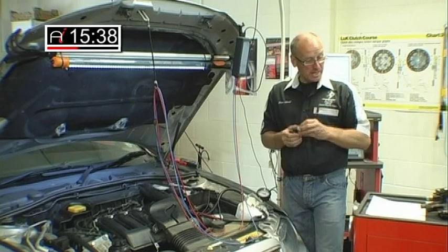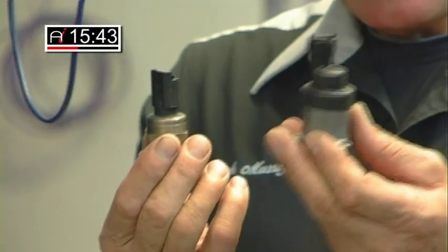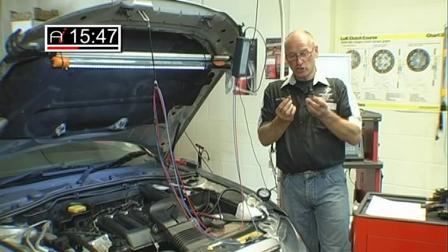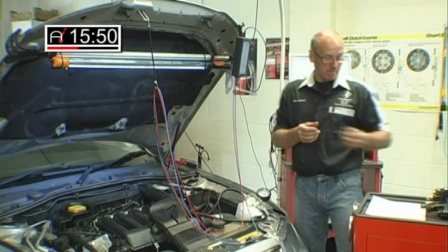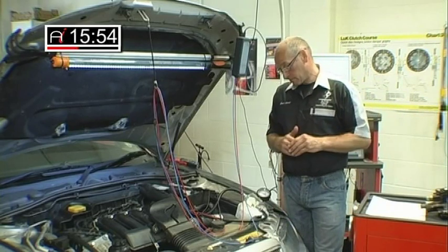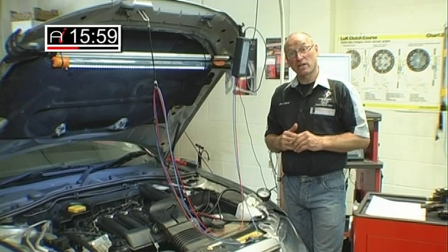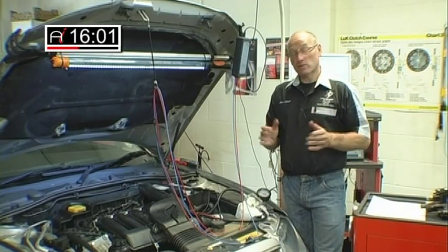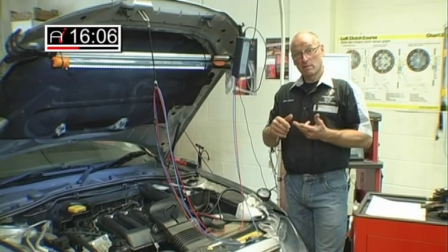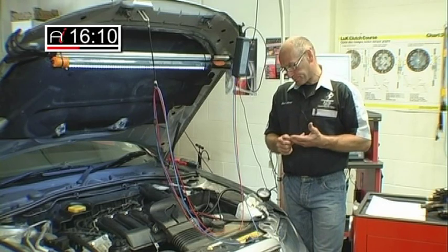Deviation, it's mechanically sticking, because the pressure sensor and the DRV work very closely in closed loop. They are each monitored very, very carefully. Then we're going to open the throttle wide open, do a simulated high pressure test, back to natural idle and key off. And that profile test, as we call it, will give us an awful lot of information about the functionality of priming, pressure generation, and to a point fuel delivery, which is the job of the injector.